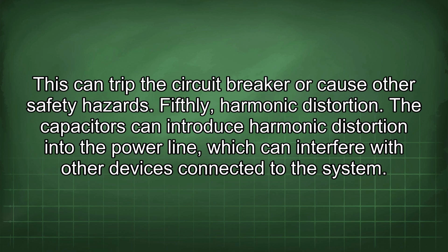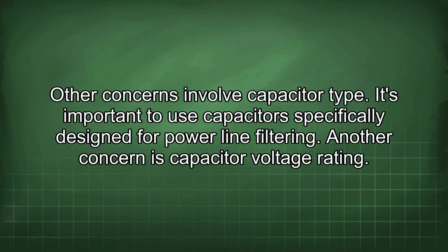Fifthly, harmonic distortion. The capacitors can introduce harmonic distortion into the power line, which can interfere with other devices connected to the system. Other concerns involve capacitor type. It's important to use capacitors specifically designed for power line filtering.